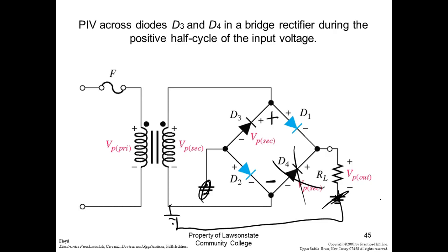Now, what you have to understand is that center tap transformers cost a lot more than the diodes do. So you say, well, it uses more diodes, isn't it going to be more expensive? No, it's going to be cheaper, because the transformers are worth the money. I don't know if y'all ever tried to buy a transformer before, but those are pretty expensive, especially when you get into your high current transformers, because they got to have so much copper in them. But then again, you'll see center tap transformers used with bridges, and that's what I'll show y'all in a minute.